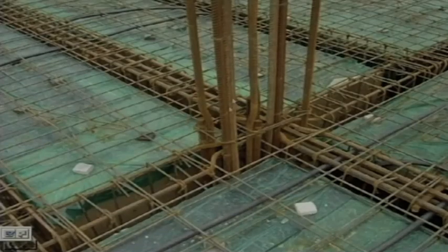Anyway, another very important thing: we are providing, let us say, 4 bars in the 4 corners of a rectangular column. Similarly, how many bars do you have to provide for a circular one? The code says that you have to provide a minimum of 4 numbers for a rectangular one, and 6 numbers for a circular one. Now, what is the minimum bar diameter? Because you have to give detailing for all those things.